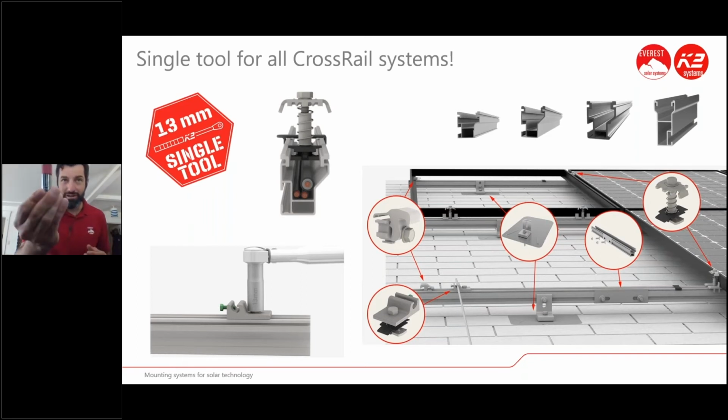Your 13-millimeter socket will actually grab a 5/16 lag bolt. If you're using a 5/16 lag bolt, chances are you're using 1/2 inch sockets on these. A 13-millimeter socket will effortlessly grab a 5/16 lag and drive it in. All I have is 13-millimeter in my tool bag, and that does everything now.